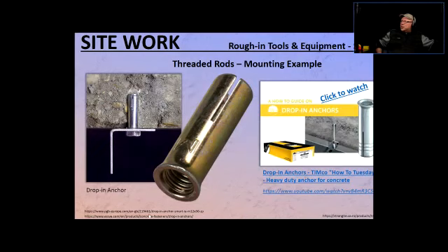Then there is a specific driver or puncture device that you insert and you hammer that in. So what happens is that when you hammer that in, this thing here expands and is held in the ceiling. And then whatever you're driving into, it just reinforces the expansion there, and there you go.